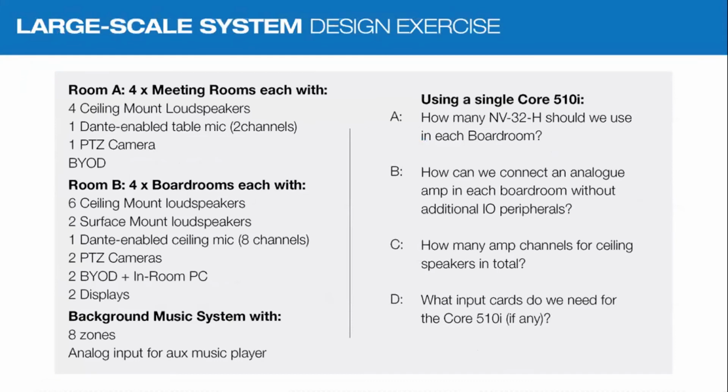So we have 4 meeting rooms this time and 4 boardrooms, as well as a background music system coming off this core. Each meeting room has a Dante-enabled table mic, a PTZ camera, a BYOD, and 4 ceiling mount speakers. Each of the boardrooms has 6 ceiling mount speakers, I guess, for speech reinforcement from the far end, 2 surface mount speakers for video playback, a Dante-enabled ceiling mic, like a Sennheiser TeamConnect or a Shure MX910, and then